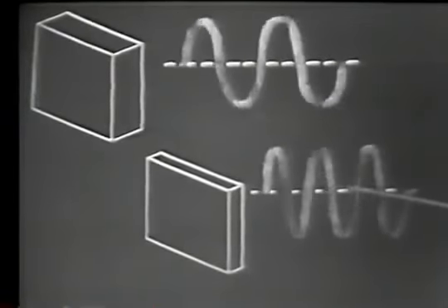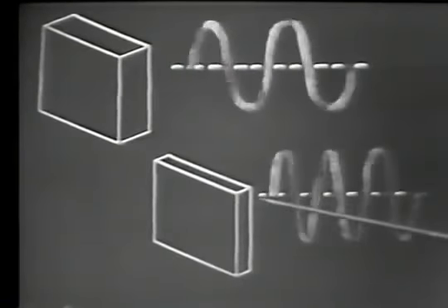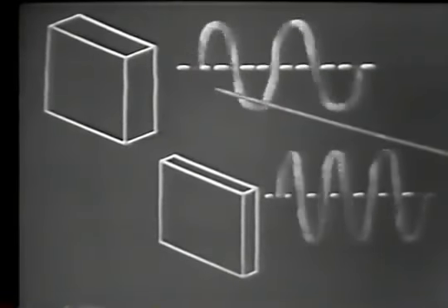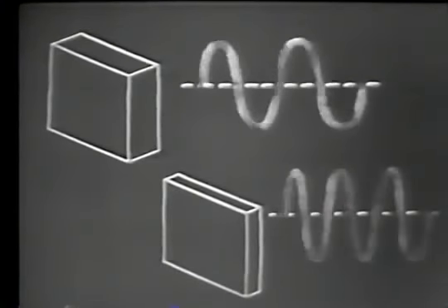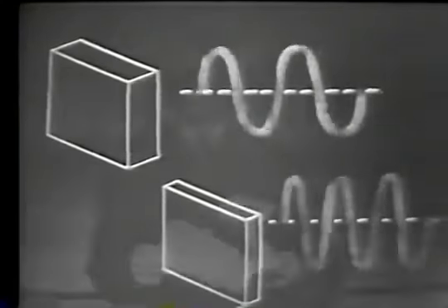We're indicating here that the vibration of this thinner cut, or the frequency, is greater than this cut. Now, this will always hold true. The thinner the crystal cut, the higher the frequency of oscillation. Okay, then at this time, let's refer to item 5 in our TVI guide. You read along with me and then complete that statement. In order to increase the frequency of a crystal, it should be cut, we just saw that, it should be cut thinner.